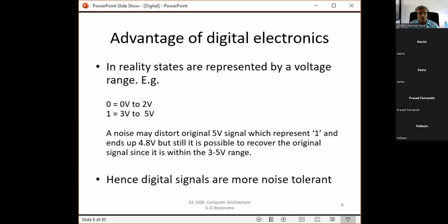These are some standards. So this one is not exactly the correct standard. There are many different standards. For example, it's not actually 5 volt. You can have up to 5.5 volt like that. So that's one thing. You have voltage ranges, and these ranges can also differ. For example, most common logic ICs, like in the 4000 series or 74 series, use voltage levels between 0 and 5.